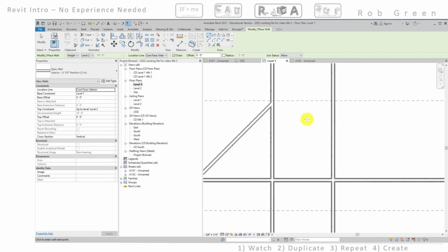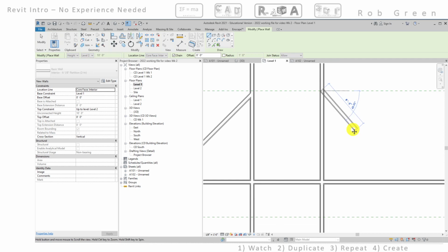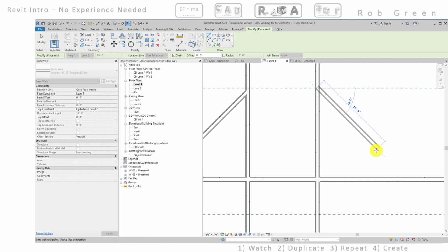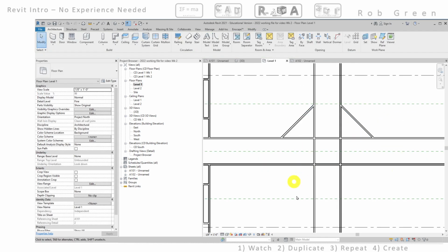So then I'm going to repeat that going the other direction. And what is important here is that I'm consistent, so I need to hit the space bar. I said the bulk of my wall was going to be on the bottom half, or below my cursor. So then I come down, and here I've got 45 degrees, double check my 45 degrees and click an end, and I have that done. So I am not going to draw the bottom two. I'll bet the textbook doesn't have it do it either. Probably has it do it with the mirror command.